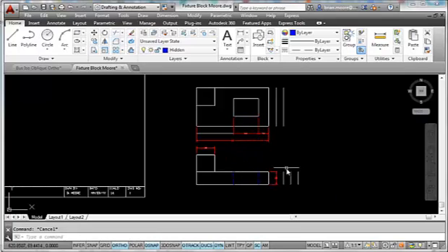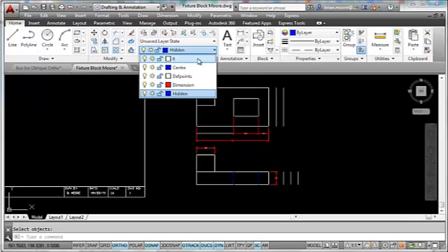And the next thing I need to do is the right-hand view. So I'm going to offset this line over by 40. So here's 10, 20, 30, 40. I've already actually got it drawn in there. Then I need to project some lines across. Should have put that onto the zero layer. So I'm going to switch back to the zero layer.